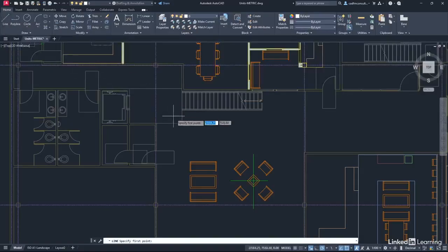Click on Line. When you come into the drawing area, it's asking for your first point. Now, the reason you can see specify first point near the crosshair is because dynamic input is on. That again is setting down here on the status bar. It's that one there. Make sure that dynamic input or DIN mode is on. Now, as you move the crosshair around, can you see that first point is being displayed in metric units, those metric millimeters. Now, I'm not worried where that first point is. Just pick a point about here near the staircase. Staircase above, chairs, sofas, etc.